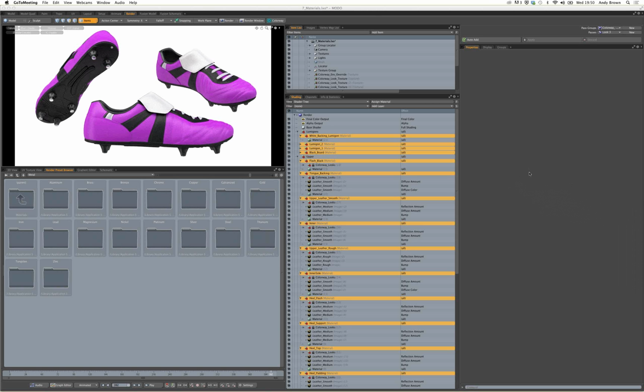Can CAD files from, say, Rhino be brought into Colorway? Well, Colorway is a 2D application, so it will only read DCI files, which is a 2D format. It's actually a deep image format. That's the technical term. And there are only two applications at the moment that are able to generate those, MODO and Cinema. They have to have a kit for either MODO or Cinema. So the only way to get a Rhino file into Colorway would be to first bring it into Cinema or MODO, and then render out into Colorway. Okay, so you'd have to go through that 3D process. Makes sense.